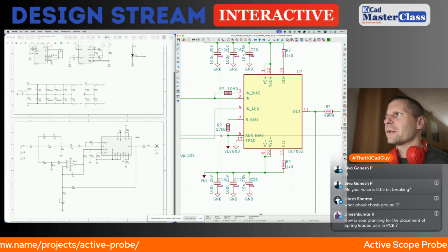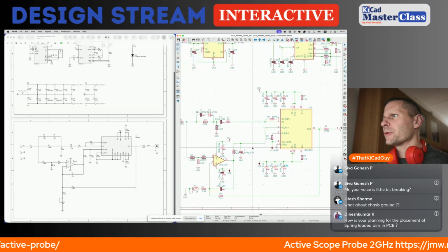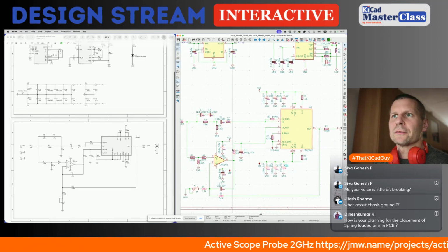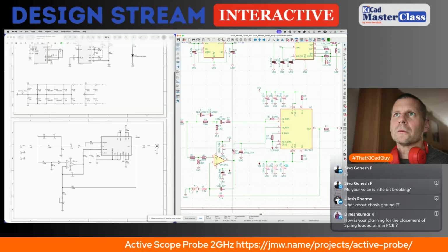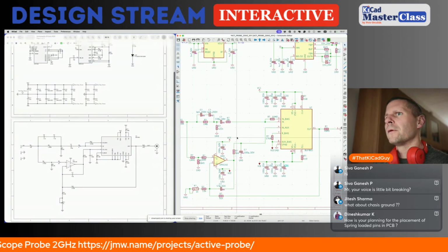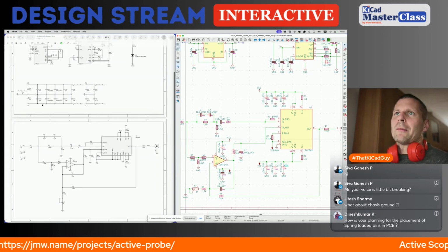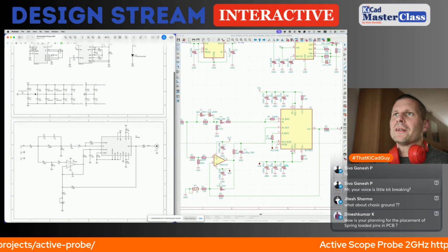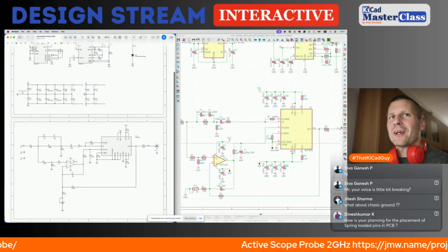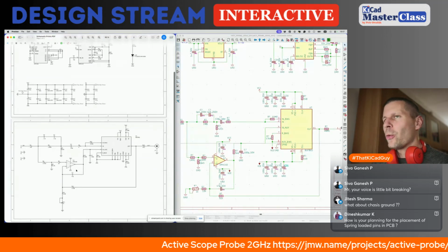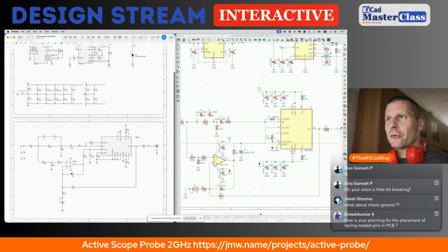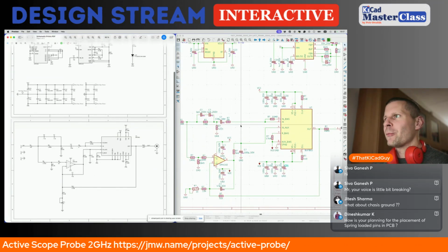There is one extra 10 nanofarads, but I don't know where to place it. As I said multiple times, don't use this. Never create a battery of decoupling capacitors without a connection to the real symbols. It's a mess and everybody will hate you.